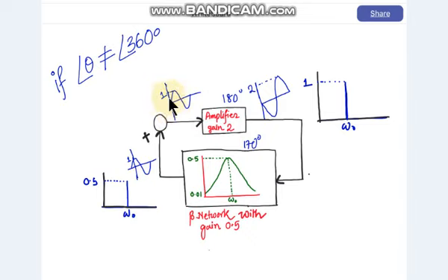Let us also assume that the input of this amplifier has a pure sine wave without any phase. So the output of the amplifier will be 180 degrees phase shifted with respect to this input. After that, this signal will pass through the beta network block, which has a phase change of 170 degrees. At the output of the beta network, the overall phase change will be a total of 350 degrees, not 360 degrees. So 350 degrees or minus 10 degrees, that is equivalent.